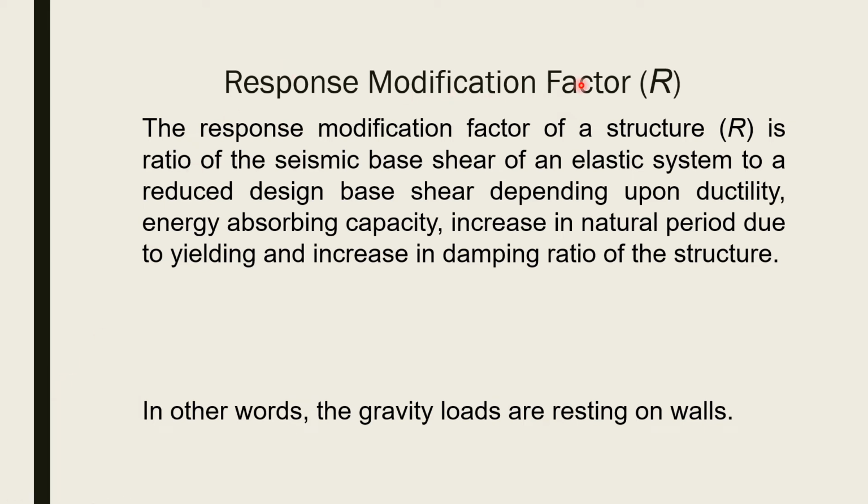Response modification factor. The response modification factor of a structure is the ratio of the seismic base shear of an elastic system to the reduced base shear depending upon ductility. Response modification factor is a very important factor. For example, if you have a base shear of 800 kilonewton, base shear means seismic force, the horizontal force acting on the structure, so the response modification factor will reduce the base shear.